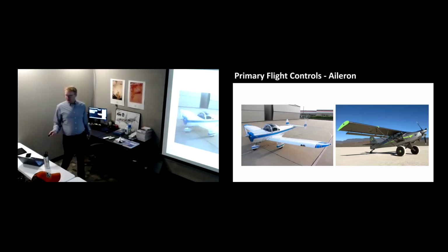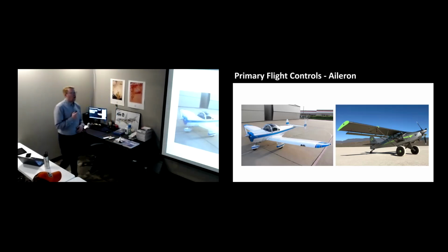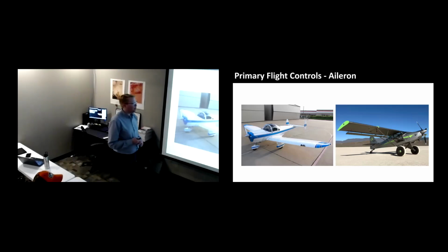Okay, this is the Aircoupe on the left, this white and blue airplane. This was the airplane that had the interconnected rudder and elevator. On the right, we're seeing an airplane that looks very strange to us. It has a flaperon setup. Notice how there's a large difference between the main body of the wing and the aileron setup, and it's also over the entirety of the wing. It's acting as a flap and an aileron, almost in combination.